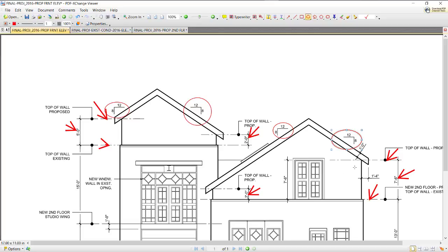And then we actually have the thickness of the roof with the rake boards and the actual construction of the roof, and that's going to be a foot thick. And then we have the overhang over here, and that's typically going to be 1'4". So because we have no information over on these sides, we're going to assume they are the same. Okay, so 12 and 8 pitch, 1 foot for the thickness of the roof, and then a 1'4" overhang on each side.